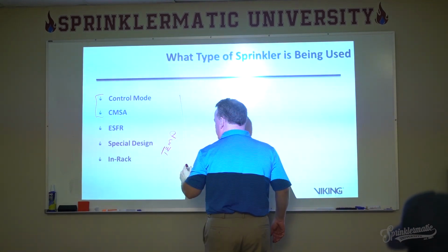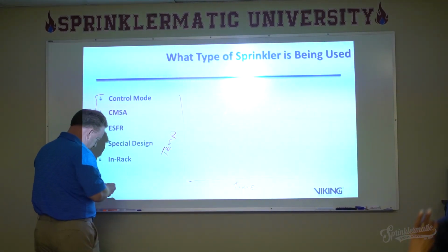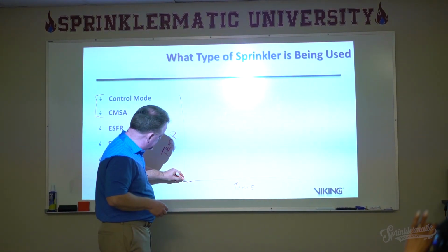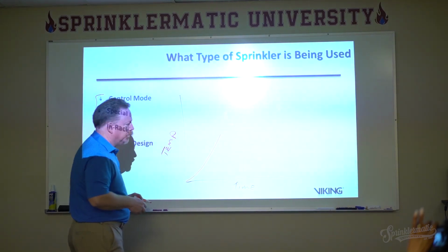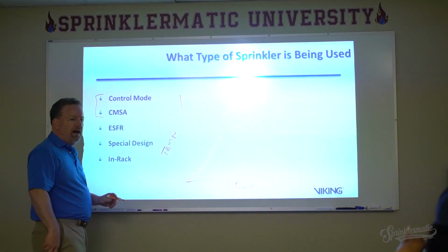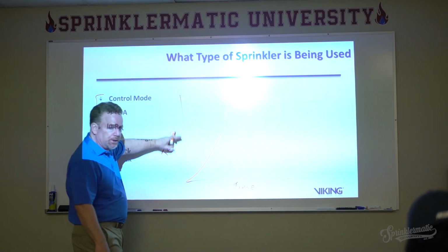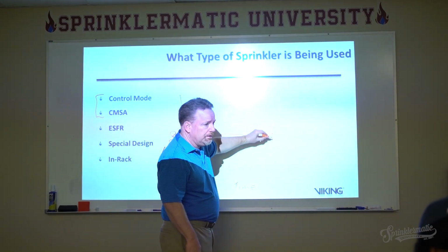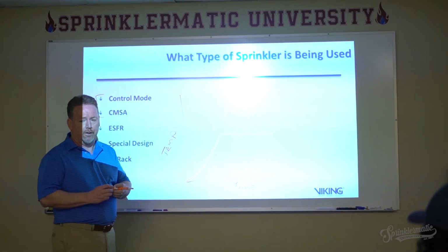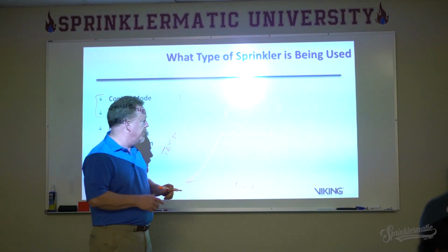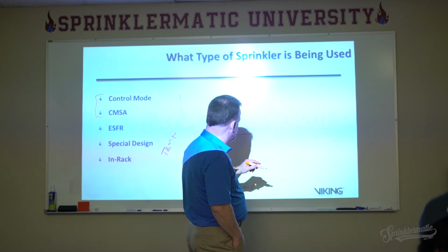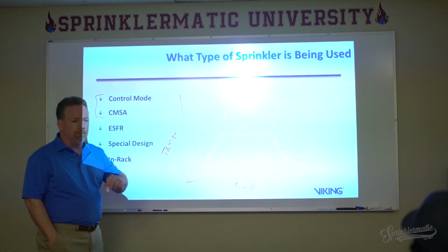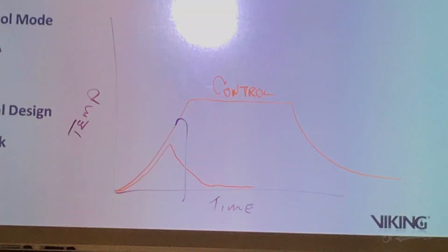we were designing sprinklers and sprinkler systems so that, over time, the start of the fire would grow. The sprinkler system would then operate. The temperature would go up, the sprinkler system would operate, and control the fire until big water showed up: the fire department with their capacity of 250 or more gallons per minute, and then the fire would go down and be extinguished.